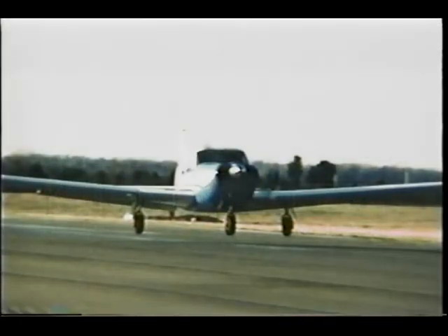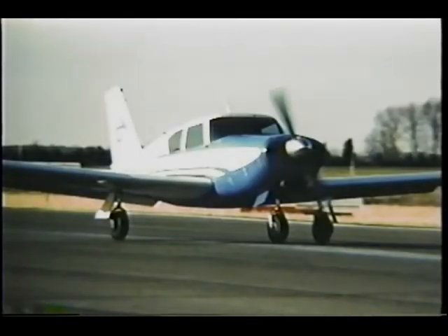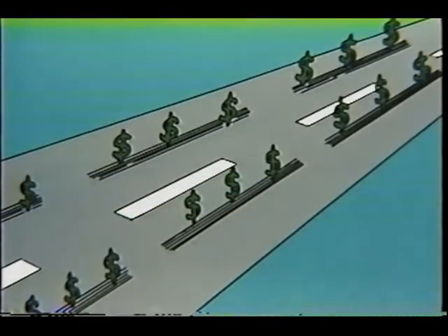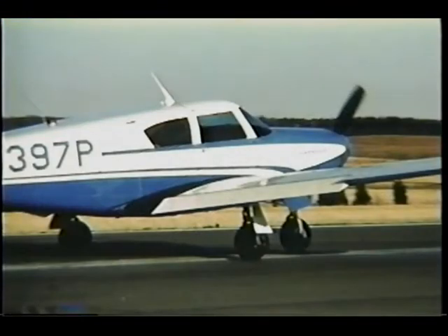In order to achieve the most effective braking, don't begin to brake as soon as you touch down. You see, right after touchdown, your airplane is still producing lift, and a premature application of brakes does little more than leave 2 expensive skid marks on the runway. You shouldn't really begin to apply brakes at all until after all 3 wheels are on the ground and the airplane is slowed enough so that it's at least 25% below touchdown speed.